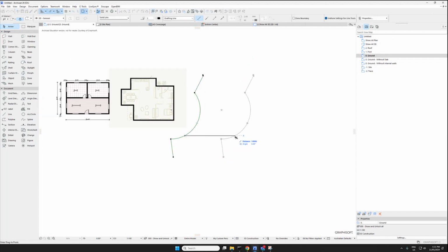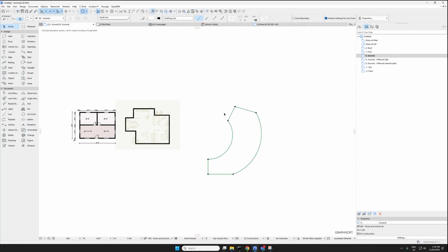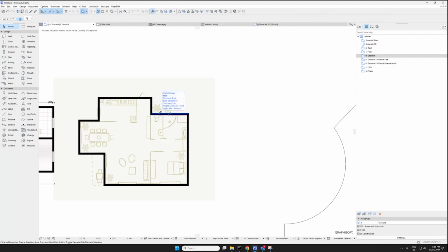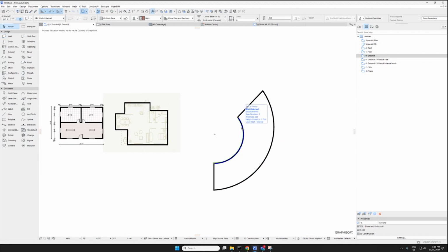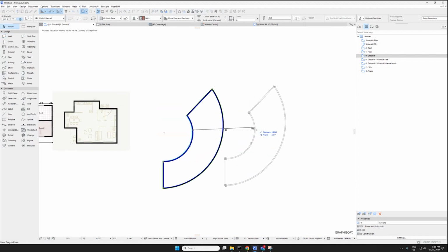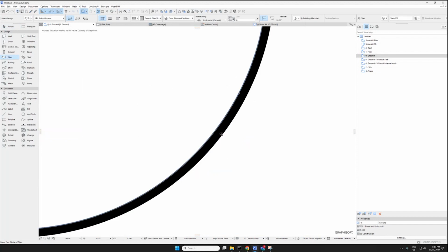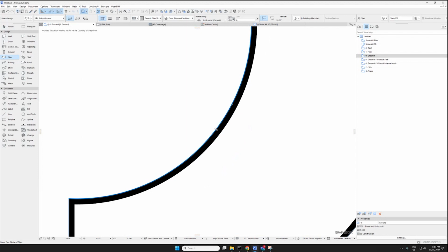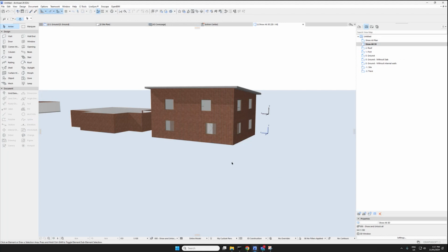And let's say move this by pressing Control D. Let's say I want a building that is like this. Put that in, hold Shift, and let's say I want my building to be something like that. I can then, by holding Alt, click on the wall, hold Spacebar, and click. So I've got my walls. It's Alt G to unsuspend the groups and pull it over. And then I want the slab to follow that as well. I can click on the slab, hold Spacebar, and I want the slab to sit on the exterior of the wall. So I've got a slab and a wall, and if I press F3, that's it there.